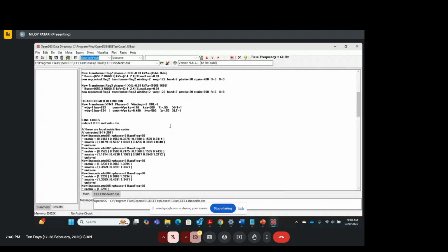But when you have to transfer that power to houses, at that point you have to put a service transformer on the pole top, and then bring that high voltage down to 480 volts or 240 volts. Generally it's a center tap transformer. I'm not going into much detail, but from that transformer onwards, whatever connections you have to each of the houses or residential customers, that is known as the secondary side of a distribution feeder.